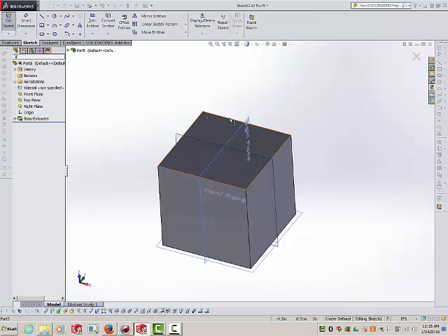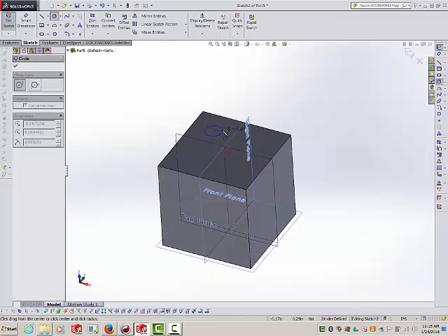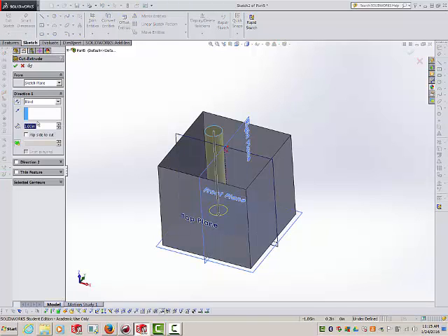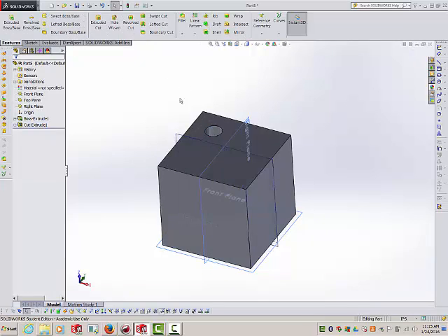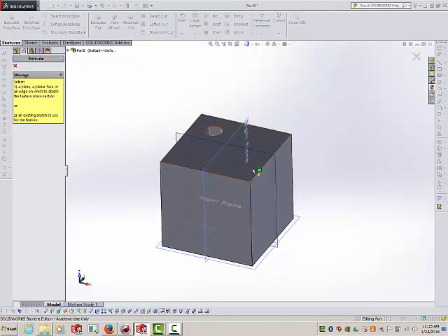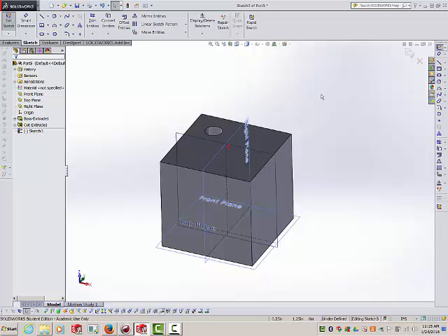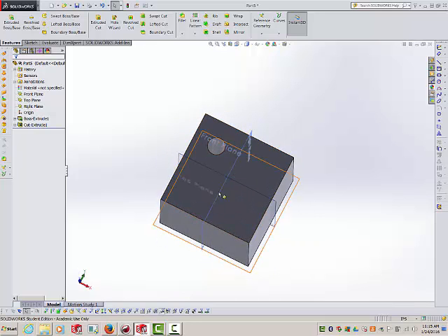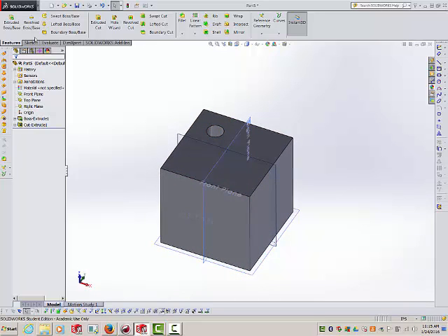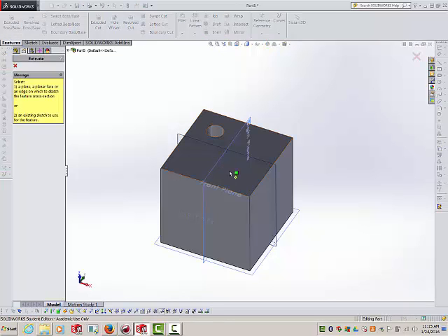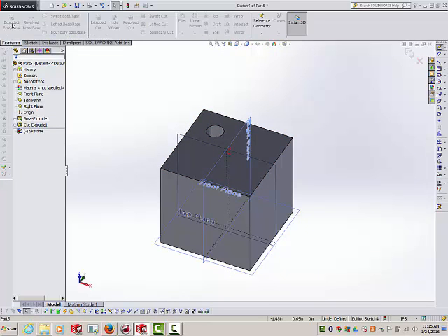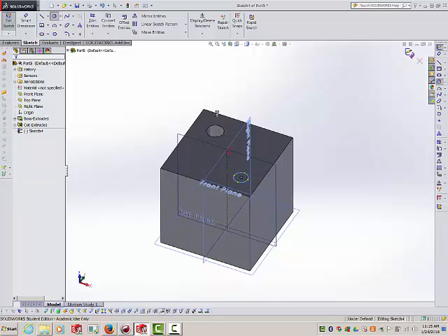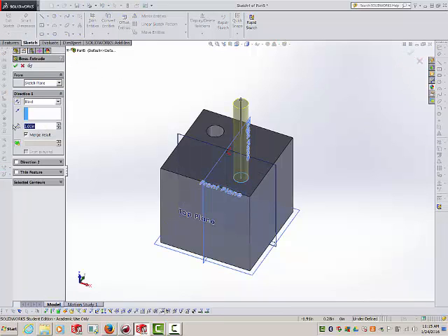So we'll go ahead and put a hole in, and I'm not doing anything precise here, just something to differentiate all this. So here's a hole, and maybe we make an extrude on top. So again, maybe this is one configuration we're selling. It's a block with a hole in it. And maybe another configuration we sell has a boss on it. Pull my sketch up here. So put another, and we'll run that boss maybe a 1/4 inch up.